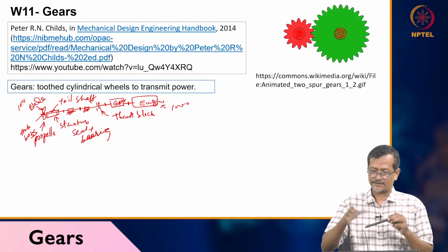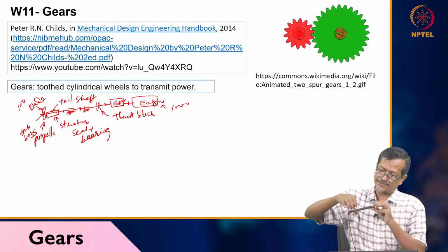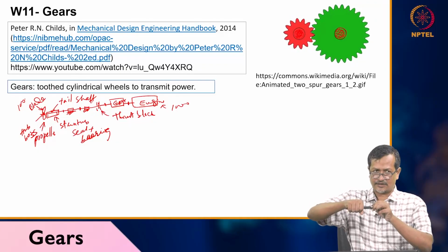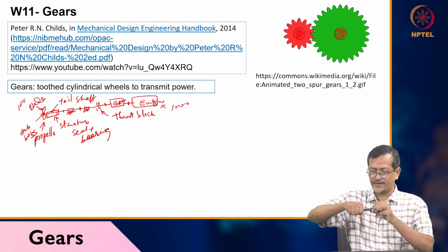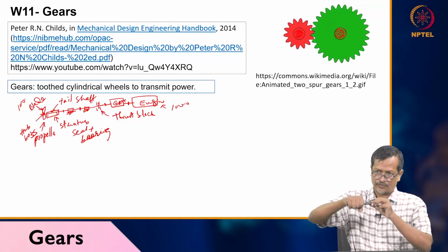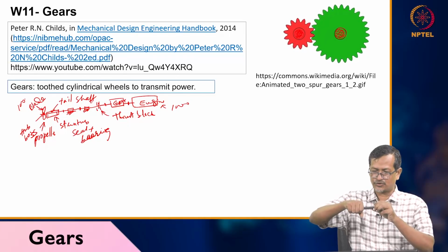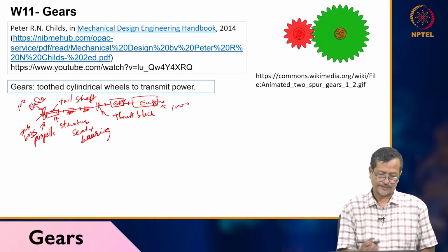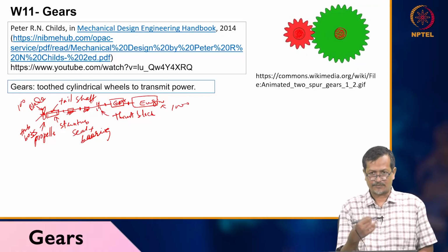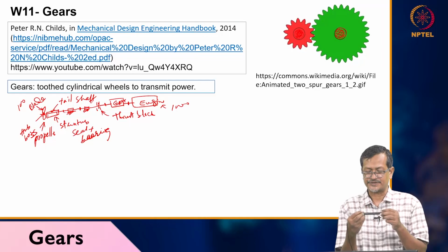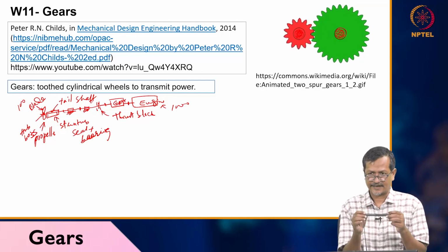Journal bearing means there will be no ball or anything; one hole is there and the shaft is here, just rotating inside. So there will be no axial load holding capacity. It will be holding only the radial loads, and it will allow rotational motion. Axial motion also possible. So the journal bearing or sleeve or muff bearing will be there near the tail shaft. That will be passing through the stern tube. The stern tube will have a sealing arrangement also.